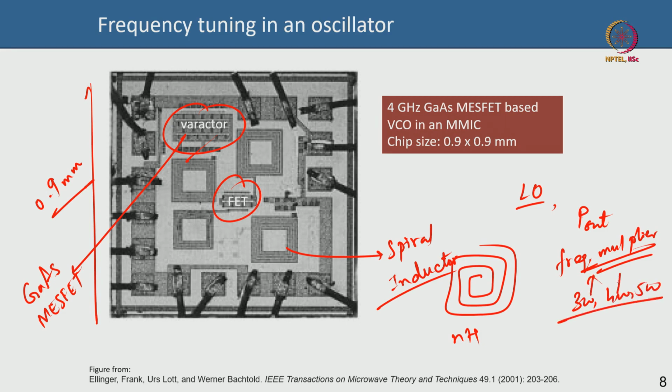These frequencies can be very high, they can go up to terahertz actually, sub terahertz to terahertz, and people can get tens of milliwatts to hundreds of milliwatts at very high frequencies, that is the frequency conversion. So, the efficiency of frequency conversion, the power that you are getting at different frequencies, whether you are terminating at different frequencies, all of these are very important, and one of the important things is called the Q factor. Q factor is basically how much energy you are storing divided by how much energy you are losing. You need to minimize the energy that you are losing. The higher the Q factor the better it is, and a lower Q factor is not a good thing.